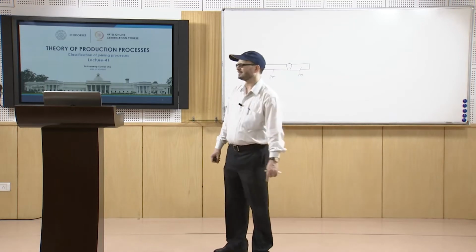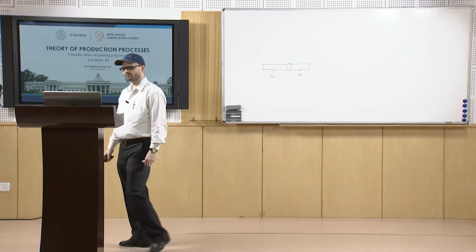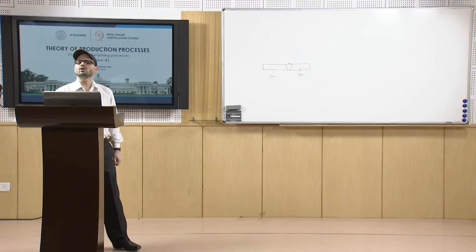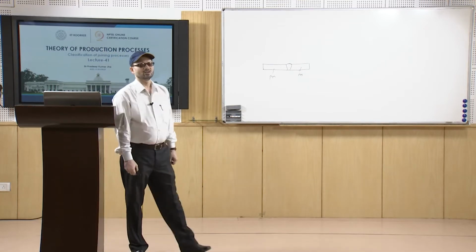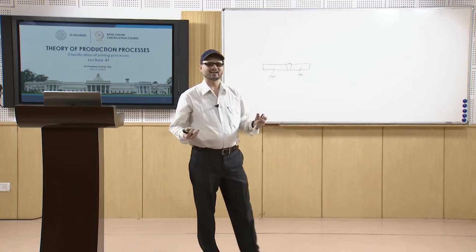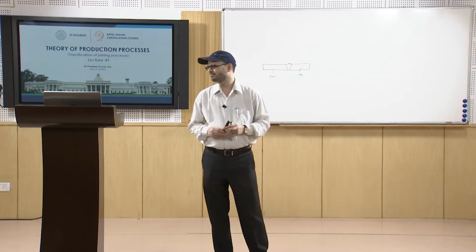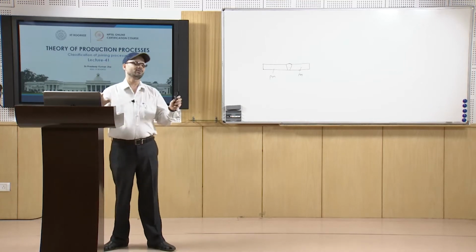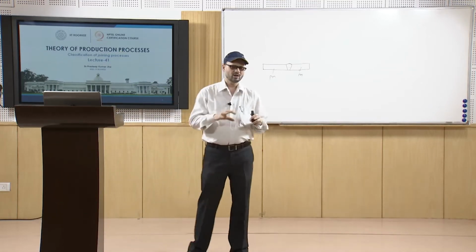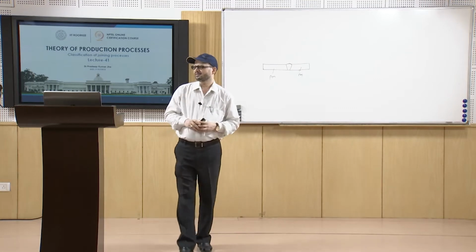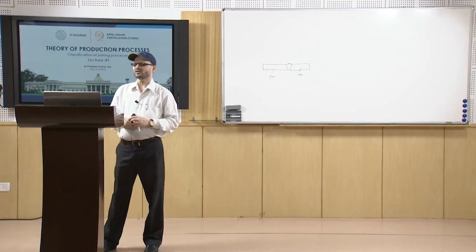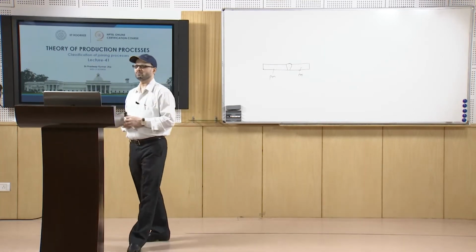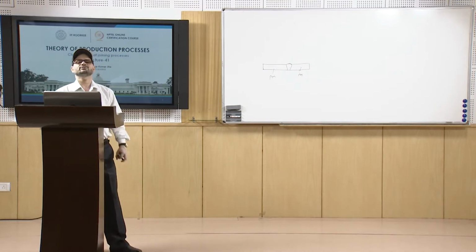So in that case you are only looking for electrodes which should be efficient in producing the arc. In that category you have different types of processes, such as gas tungsten arc welding or tungsten inert gas welding, that is TIG. Here tungsten is used as the electrode, and an inert gas is used as a medium for protecting the weld pool from contamination. Then you have plasma arc welding and stud welding. These are examples of non-consumable electrode type welding processes.